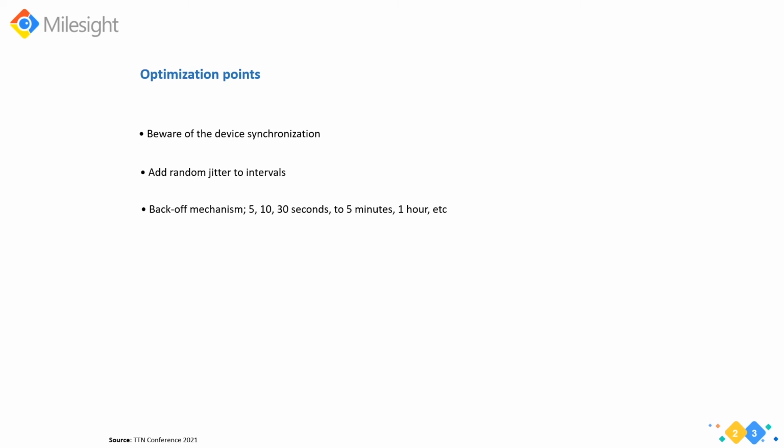At first, if your end device joins a network, you can send a join request after about 5 or 10 seconds to make a try. But if the end device fails to join that network, please stop and retry after hours.